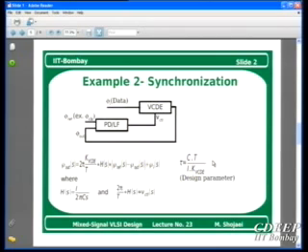What does it say? It means that the time constant of this loop to settle is a function of C over I, which is expected. If C is less and I is more, I will have less delay. But at the same time, my filter will have a higher bandwidth, which is not good for the input jitter, for example. And then the sensitivity of the delay element: if I have more sensitivity, the loop will settle faster.